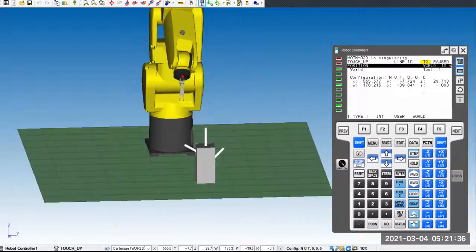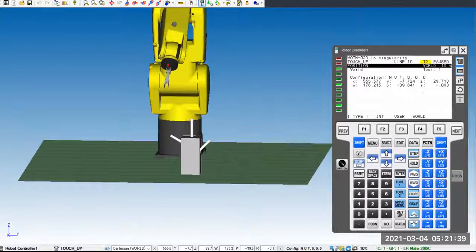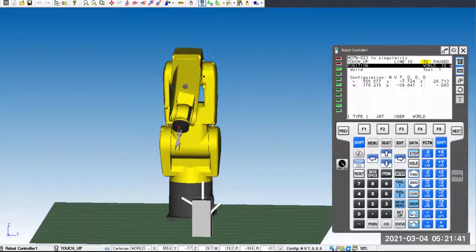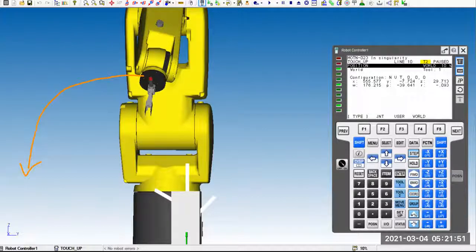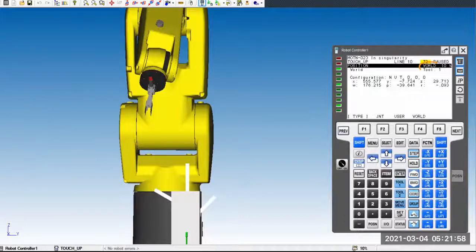And if you look at the front, I'm trying to pick up from the left. So maybe I'm supposed to rotate on this side a little bit. Let me get a pencil. Maybe I should rotate this side a little bit to get ready to pick up from this angle, right? For that, because I'm in roll, second right hand rule, that means I have to rotate around X. And if you're familiar with the second right-hand rule, I should rotate around X in the positive direction.